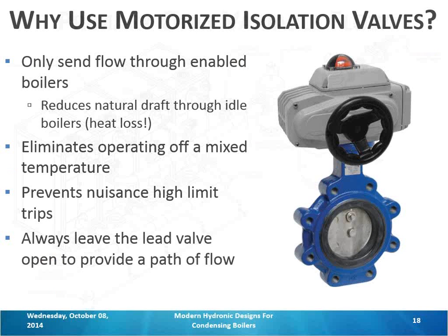To get the heat out? It depends on the mass of the boiler, your system temperatures, your glycol. I mean, there's just so many factors. But low mass, less than a minute, 30 seconds to a minute. A high mass, 5 minutes maybe. Also depends on your outdoor temperature too, because if you're out in Minnesota and it's negative 30 degrees, and you go through a 1-minute purge, that sucks a lot of heat out of that heat exchanger.